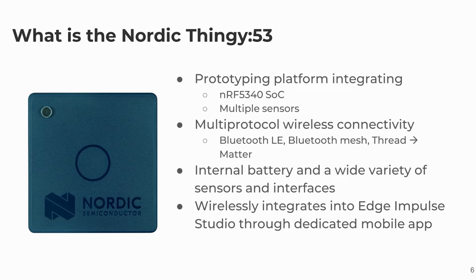By using the nRF5340's built-in radio, we can connect the Thingy:53 to our nRF Edge Impulse app that both uploads training data to Edge Impulse Studio and also downloads fully trained models back down to the Thingy:53 after you've built the model.